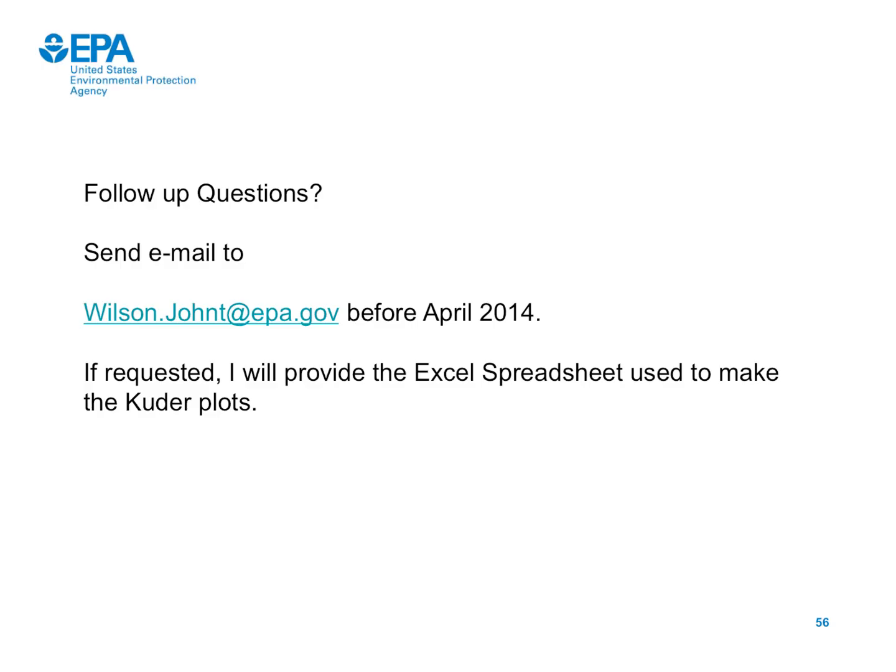And this is basically ORD guidance that went through the EPA clearance process. And what it says is that you take all the wells and you look at the concentrations and you look at the trend lines and you see which well is the one that's likely to be the last one standing with concentrations above the action level. And that's the one you worry about, because that's going to be the one that limits how long it takes the entire site to clean up. So if you have a well that's trending the wrong direction, but it's way down there in the concentration list, that's not the one to worry about.